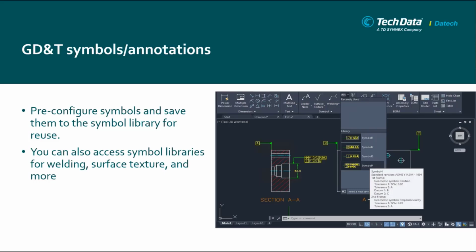However, the drafting standards and the revisions of the symbols you are importing must be the same in both drawings. During the importing process, you can choose whether you want to replace the entire libraries, or append or override the symbols. If you choose to replace, the AutoCAD Mechanical Toolset data is replaced by deleting the libraries and replacing them with the imported ones, or you can import the symbols by the name of the existing ones.